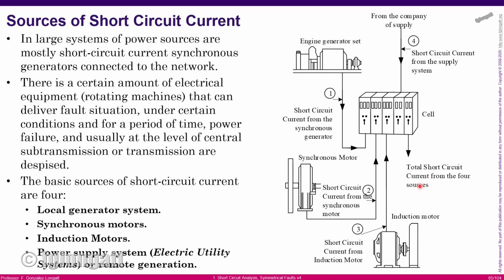The first thing that you need to realize is that when there is a short circuit inside a power system, any AC rotating machine directly connected to the grid will contribute current to the fault. I will say again, when there is a short circuit inside your power system, and I am not talking about three phase, I am talking about any kind of short circuit fault.